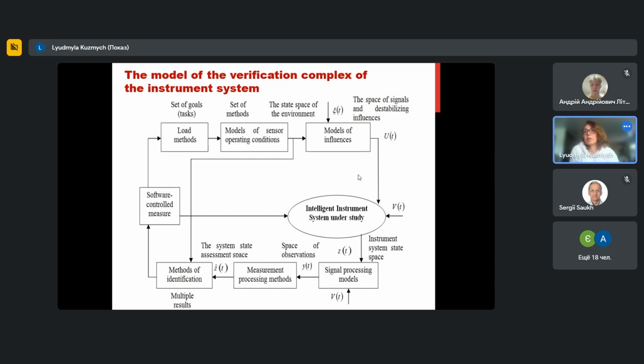The signal observed at the output of the tester is converted into digital code and compared with the code of the test signal. Based on the comparison of the codes, the error at a certain point of the measurement range is determined. The procedure according to which the processing of measurement results is carried out according to a certain software algorithm is repeated at each reliable point of the scale of the measuring instrument.